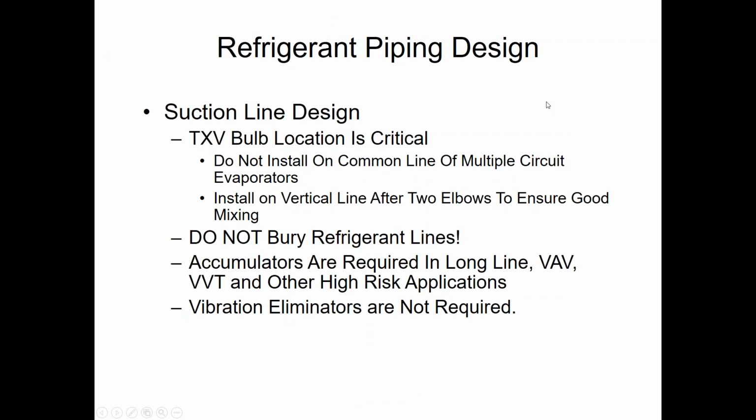We'll talk a little bit about TXV bulb location. Talk about multiple circuit evaporators coming up here real soon. And did I mention not to bury refrigerant lines? I'm not sure. If not, don't bury them. Okay, not allowed.